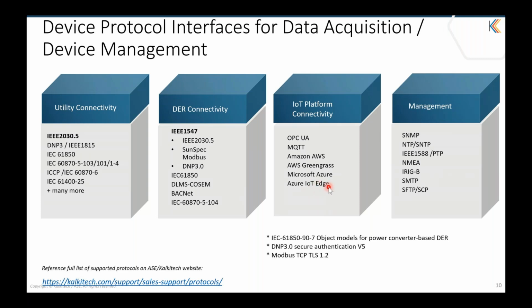which enables users to expose data to a third-party system, and it also supports other standard protocols like OPC UA and MQTT if we want to have other standard-based protocol integration support. And there are a lot of management protocols like SNMP, SFTP for file transfer, NTP or SNTP or IEEE 1588 for time synchronization. All the management-level protocols are also supported in the gateways.